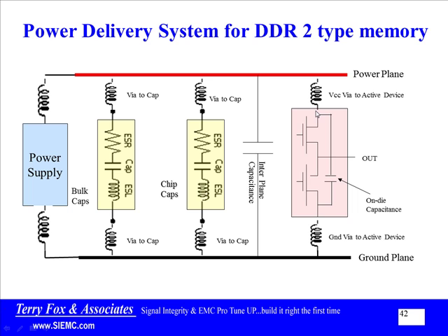But for most of us, we are faced with the fact that we don't know what the on-die capacitance is. We need to build something back here that will make it work. And so consequently, you get into a situation of saying, well, all right, if I don't have the information here, I need to have some sort of strategy that makes sure that if this chip works on anybody's board, it works on my board. So that's where we'll go from here.